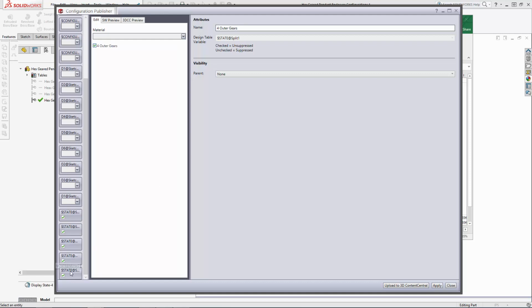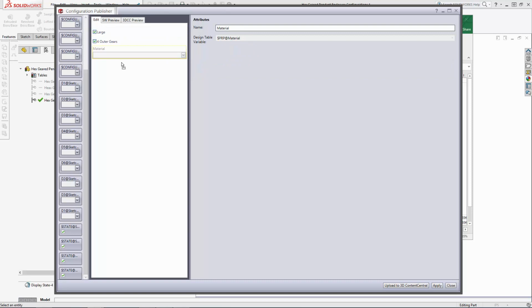The last control I'll pull is for the scale variable, which will allow us to designate either the small or large version of the pendant. Here again, if the user checks the box, this variable is unsuppressed, meaning the scaling operation will take effect and create the large version of the pendant. So I'll name this control large. If you're a little confused by what all of this ends up creating, don't worry. It will all click once you see the results of this in the assembly environment in part 3 of the series. So with our controls set, go ahead and hit save,